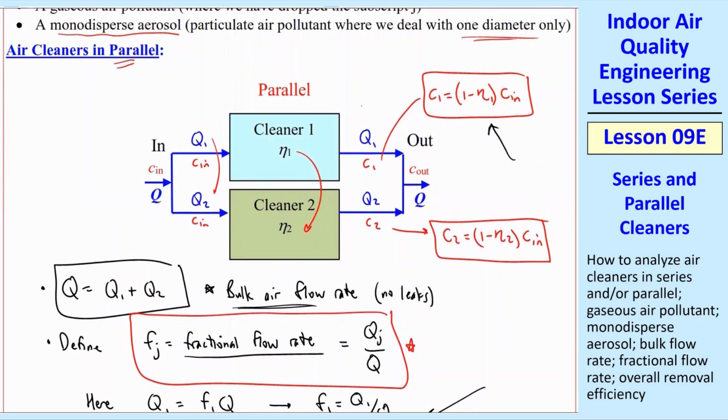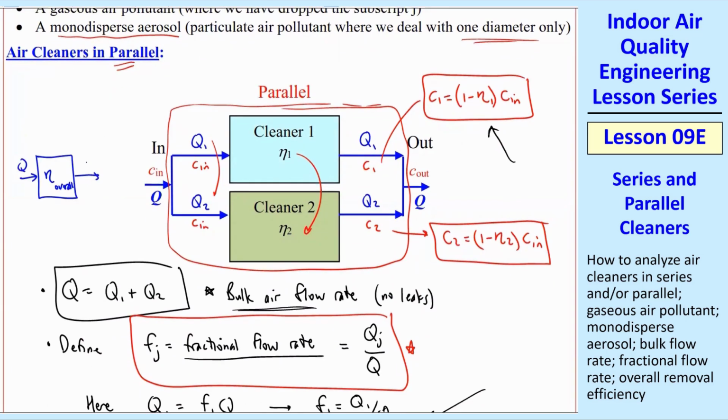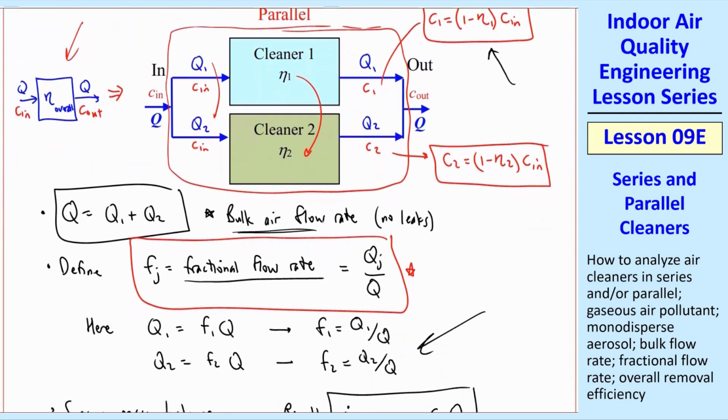What we're essentially saying is that if we put a box around this whole thing and assume that this is just one big cleaner, this is equivalent to a cleaner with flow rate Q and mass concentrations C in and C out. You can even physically put both of these cleaners, as in this schematic diagram, in a box so that you don't even know that there are 2 cleaners in there. You just see this. That's what we're trying to get, the overall efficiency.